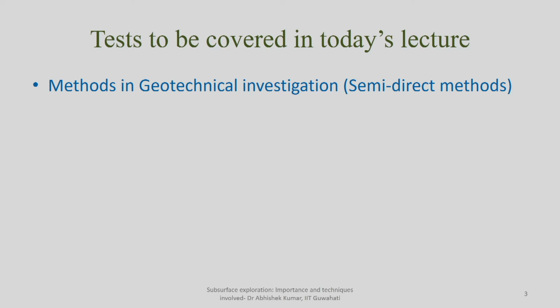When we started our geotechnical investigation, we talked about the different methods which can be used. The direct methods were trial pits and test pits, where you actually go to the site and dig out the sample, where you can see the stratification in its natural condition, see the soil layers in different conditions, and report it with respect to some nearby structure, with respect to the depth, and so on and so forth. Those are called direct methods.